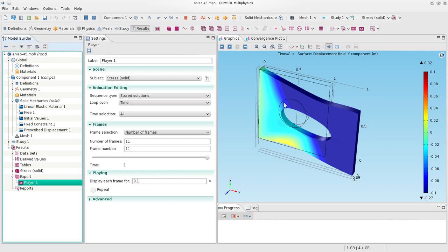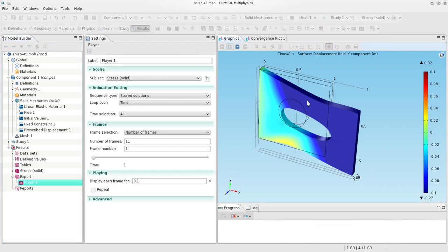In this case, the orientation of the fibers is at an angle that's skewed to the x-axis, but still perpendicular to z. You don't get any motion along the z direction. Still, motion along z is 0, but now there is motion along the y direction, and in particular, it moves down, all right? And it's free to do so, so it does, but it didn't do it for the case of isotropy or for the case of orthotropy with a fiber orientation parallel to x. It did so because the fibers are now running at an angle of 45 degrees, okay?